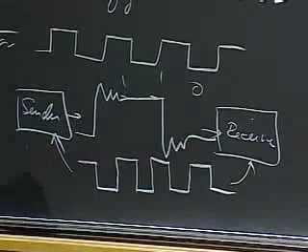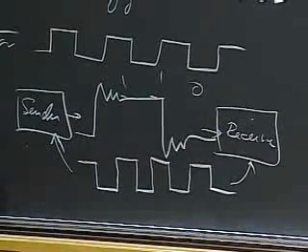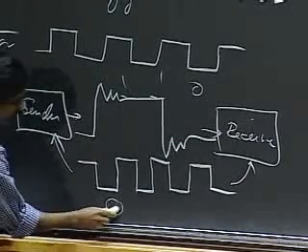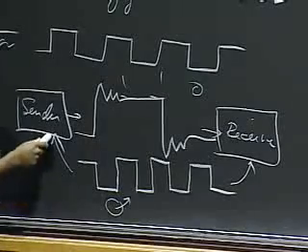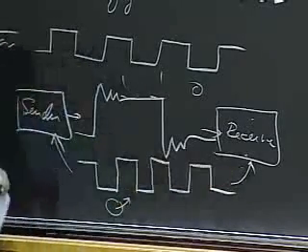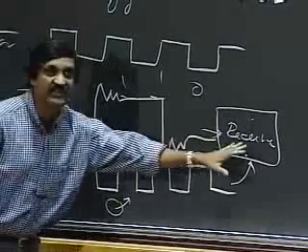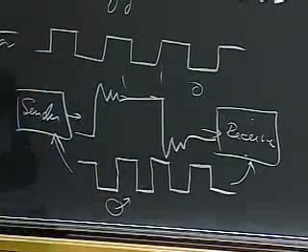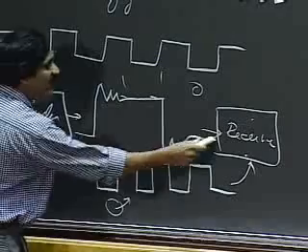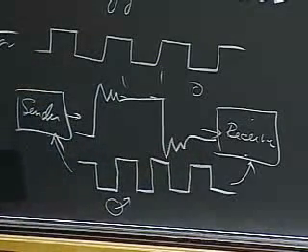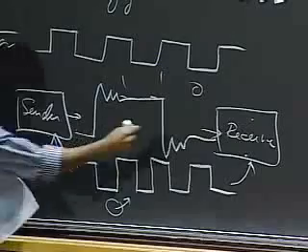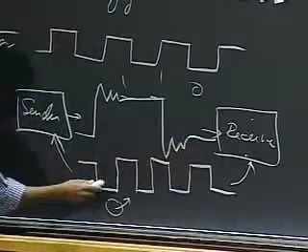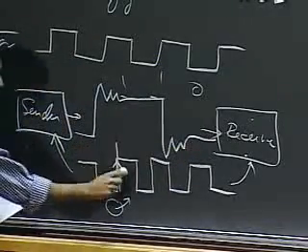A clock provides a notion of time to the circuit. I have some kind of a clock signal generator, and I connect that to the sender and to the receiver, and now both the receiver and the sender have a notion of time. And what I can do is tell my receiver, the sender and the receiver can have an agreement between them that says: look at the signal at your input on the rising edge of the clock.